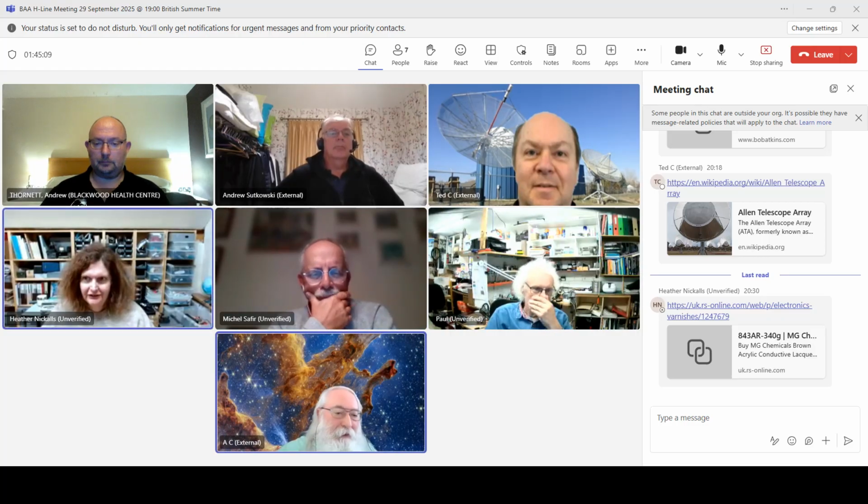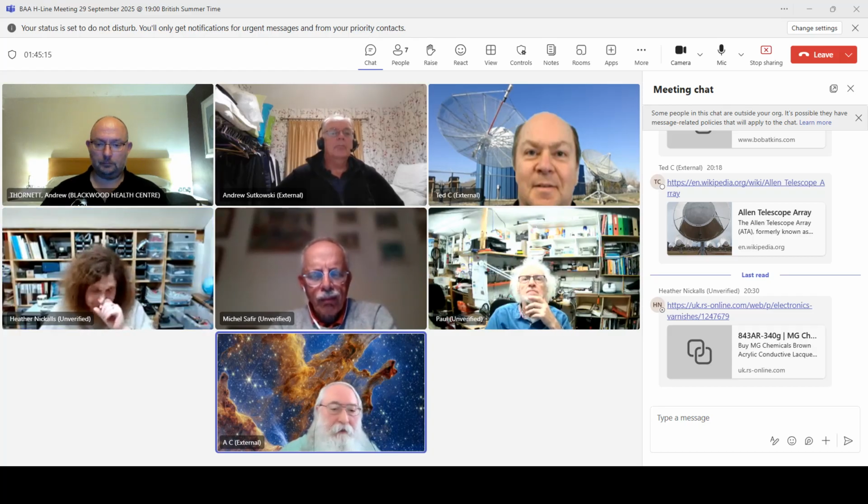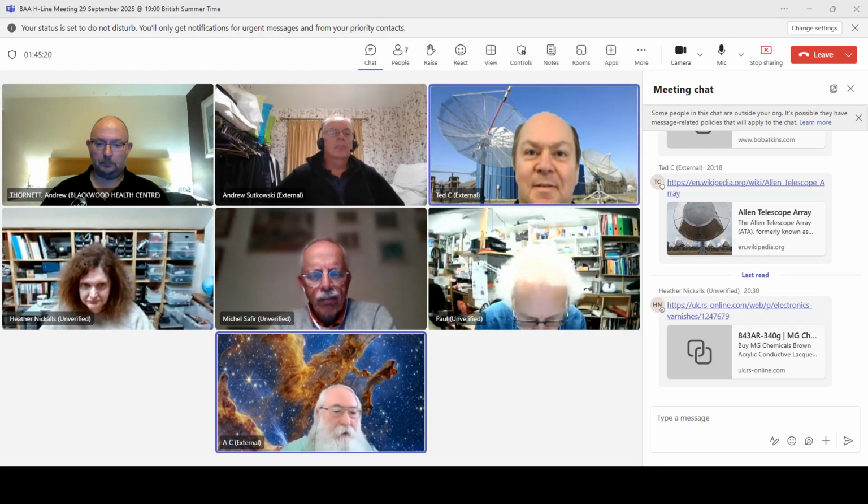But if it's an appropriate size dish, of course the same rule applies for the size of the reflector. I believe usually you want at least 4 or 5 wavelengths for the size of your reflector. Anything much below that is just not really doing pretty much anything.